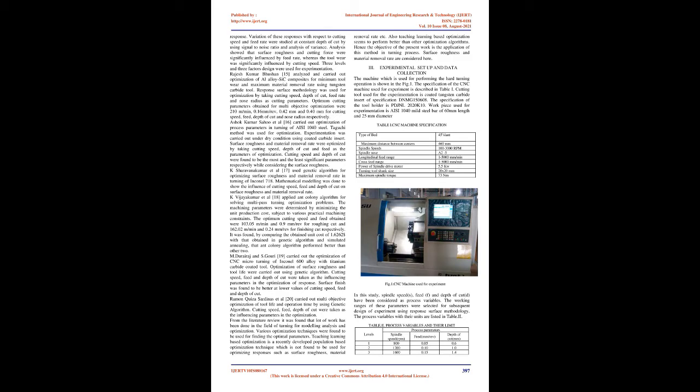Hamdi Aouici et al. [12] carried out the optimization of surface roughness and cutting force components in the hard turning of AISI H11 steel. The effects of cutting speed, feed rate, depth of cut and workpiece hardness were experimentally investigated, taking surface roughness and cutting force components as responses. Response surface methodology was used for mathematical modeling and optimization of responses. The study showed that feed rate and workpiece hardness are the significant factors affecting surface roughness. The feed force and the cutting force are strongly influenced by the depth of cut, whereas the cutting speed had very small influence. Ilhan Asiltürk et al.